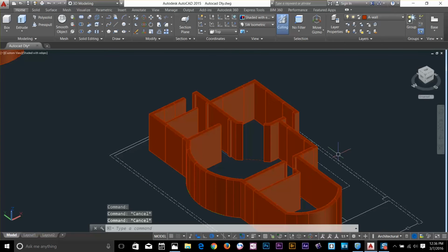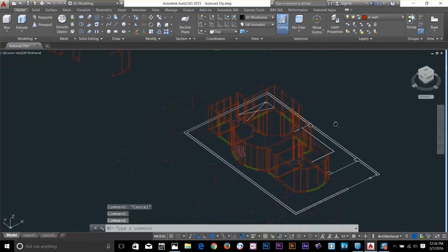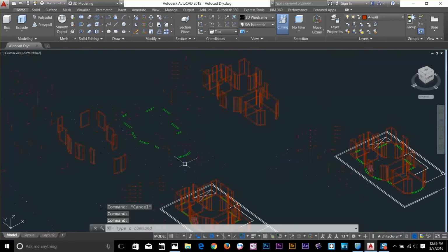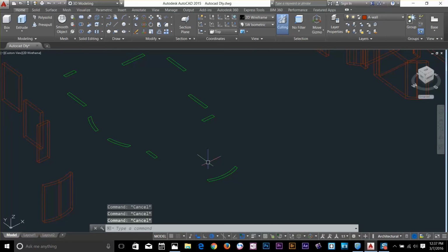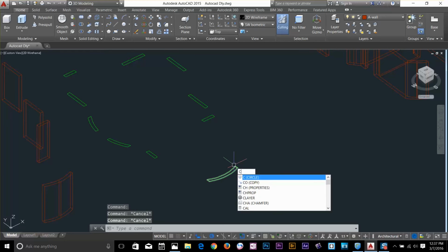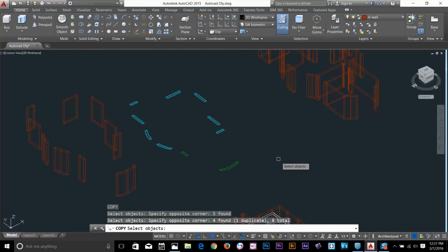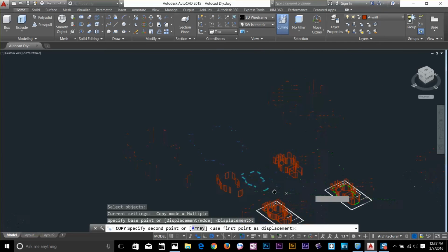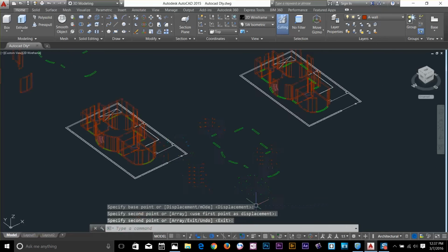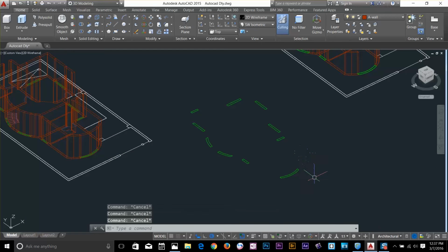Now let's cut some edging for the windows, alright? So now go back to your 2D wireframe viewport, and now you've got this window. With this window, I want to make another copy. And now just leave them here. And now we're going to apply a Boolean operation which is called subtraction.